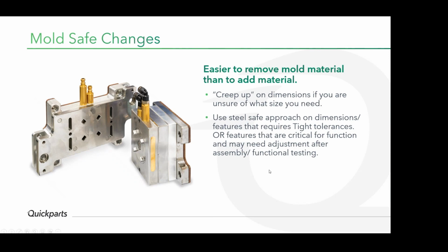Sometimes you just need to change the insert. So that's expensive. So identify those features upfront so that they can be kept steel safe and dialed in quickly after the tool trial is done and samples are made. Next.